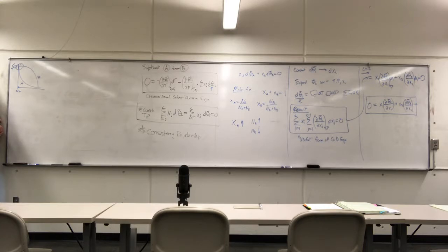You say A. Why do you say A has a greater flux away from the wall? Why? Slopes deeper. What's the flux of B? 0. Yeah, there's no flux away from the wall in the B case. So if this is, let's say, a hot plate, and this x is the distance away from the hot plate surface, which of these two is a better representation of the temperature profile?